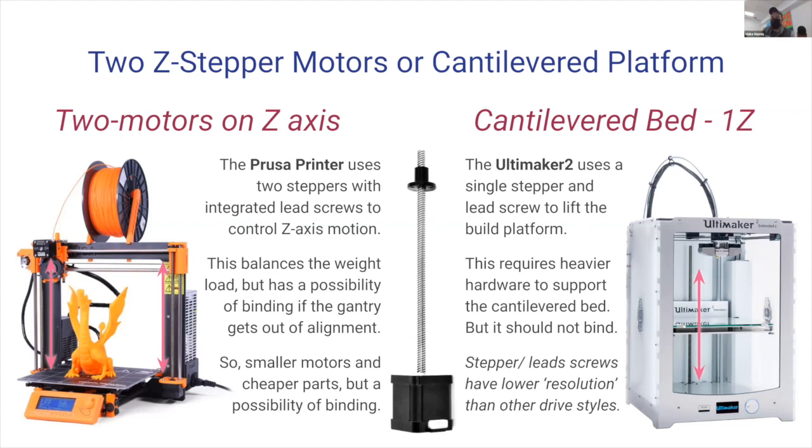The practical consequence is that if you're 3D printing something and you talk to the 3D printing facilitators, they're just going to flatly tell you, oh, the Z-axis has always got the worst resolution because the belt-driven gears have better resolution, and the Z lead screws, they just can't get as many steps into 1 inch of motion, or a few millimeters of motion. It's an interesting consequence of the way that they're built.